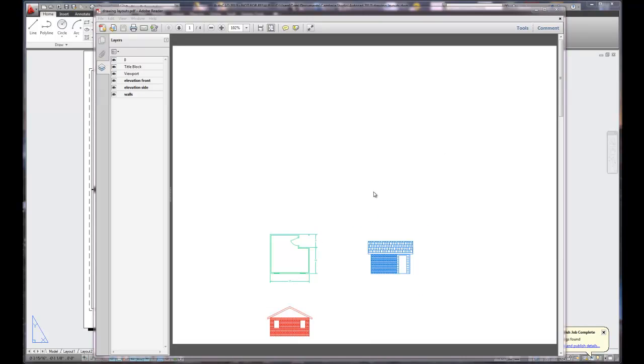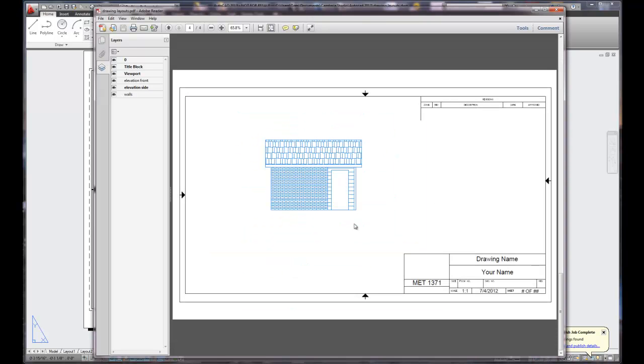And so when I open up the PDF file, it's got all 4 sheets. So it's selected all 4. And they are to the scaling factor that we selected. And so it makes it fairly easy to do and manage when you're working with this. That's about all from here. The key is to practice with making multiple layouts, being able to control layouts with viewports and scaling, and then output to a sheet set like a PDF package. Have a great day.